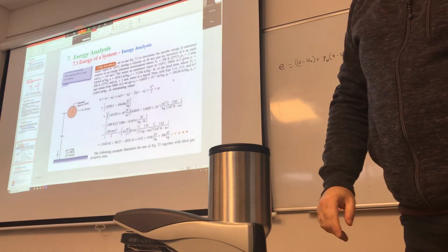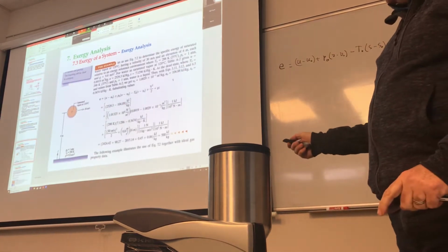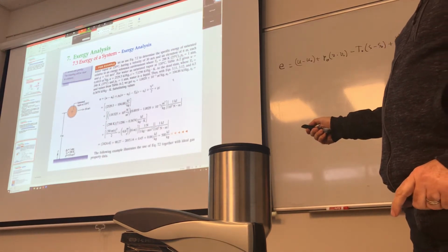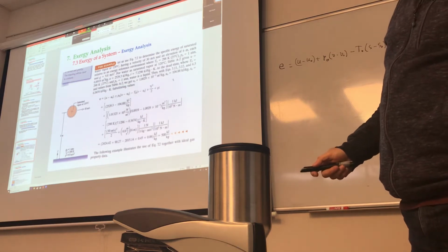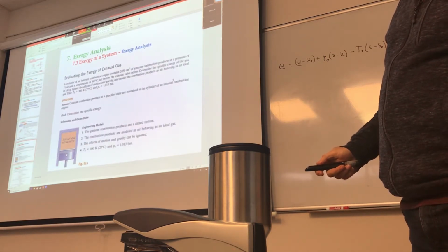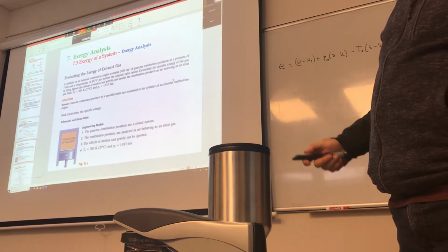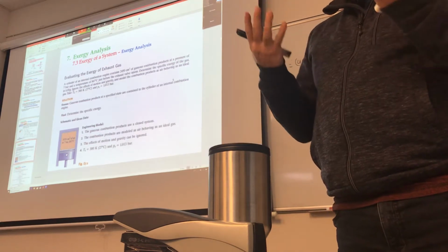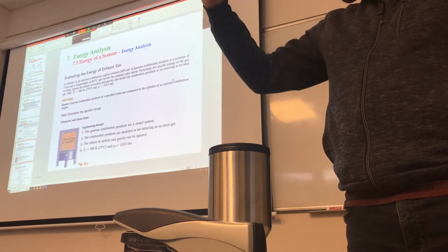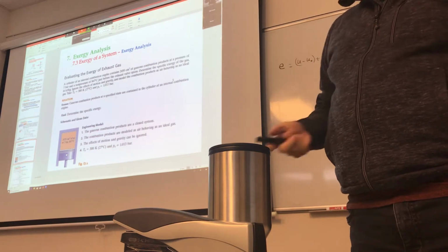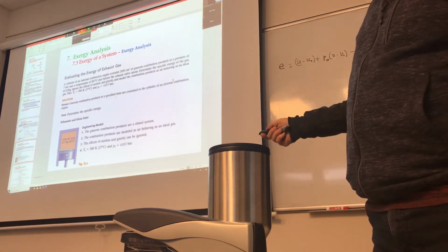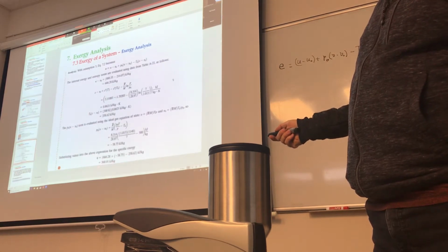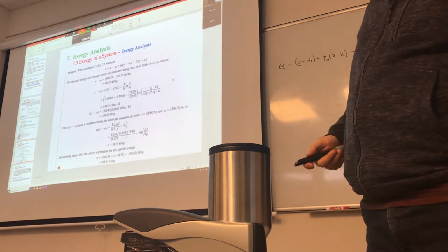And then we looked at one example of how to calculate the exergy of saturated vapor at 120 degrees by applying this simple equation, and we came up with the answer. We also looked at an example evaluating the exergy of exhaust gas, because as you know, exhaust gas is really hot, and that means it has potential for energy. But once it's discharged in the atmosphere, that's it, it's gone. It's at a higher temperature and a higher pressure, and we came up with an answer of approximately 368.9 kilojoules per kilogram.